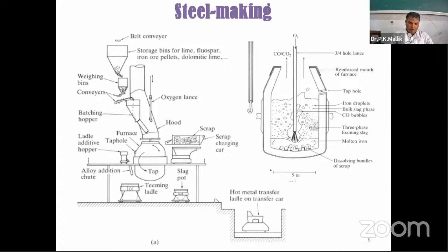For example, mass transfer of carbon to the scrap metal surface effectively dissolves the light section scraps even though bath temperatures are below the melting point of the scrap during the major portion of a blow. However, when the bath temperature exceeds the scrap melting temperature, around 1700 to 1810 kelvin, normal thermal processes involving turbulent heat transfer take over, and the scrap finally becomes assimilated into the molten bath.